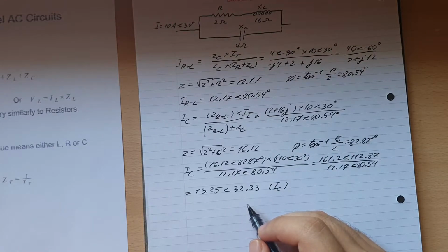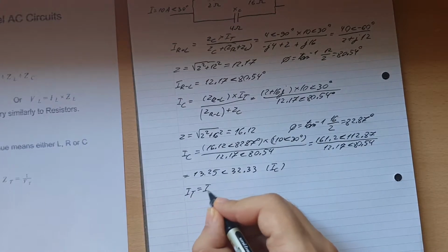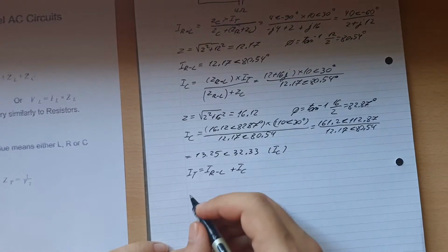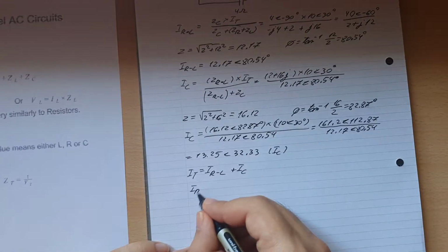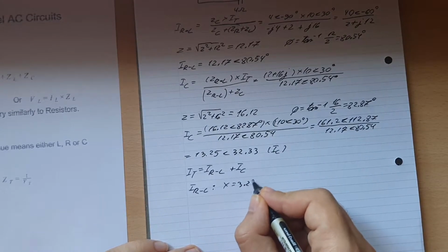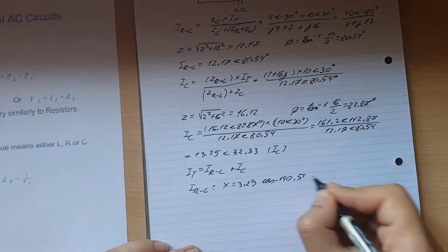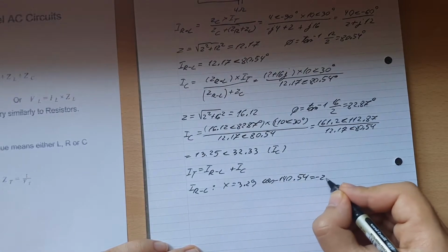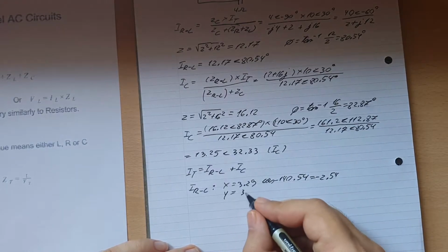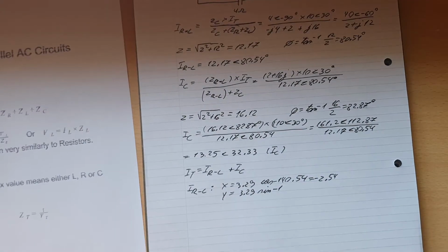And we can actually check our answers by simply doing IT equal to I_RL plus IC. So then for I_RL, X will be 3.29 cosine of minus 140.54, which is equal to minus 2.54, and then Y is equal to 3.29 sine of minus